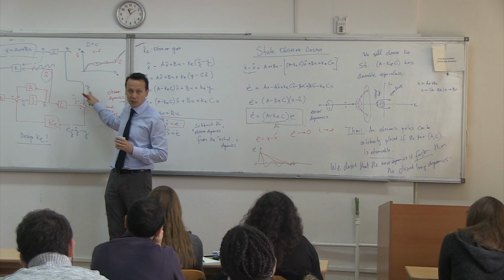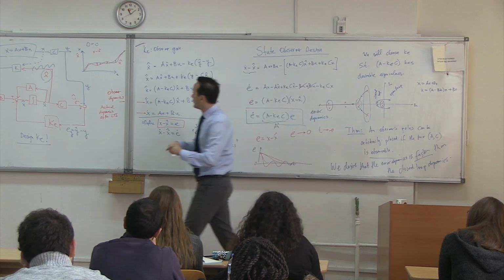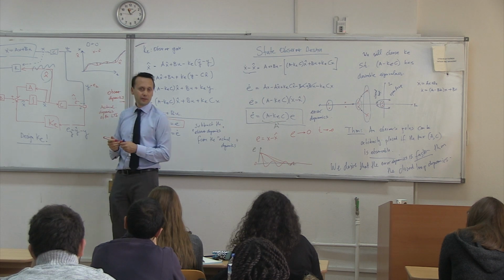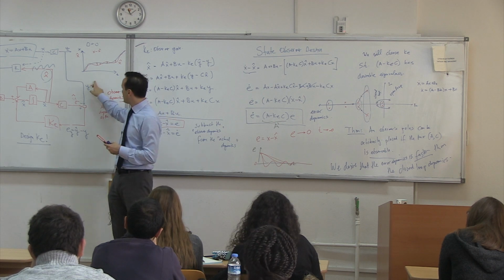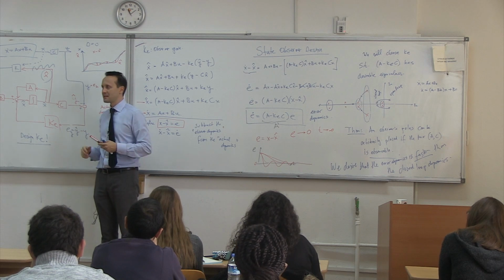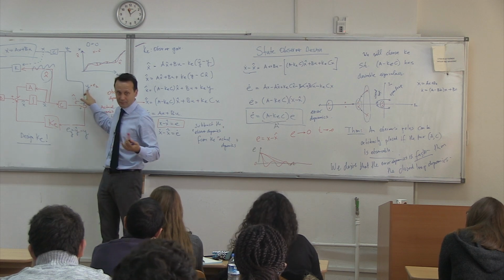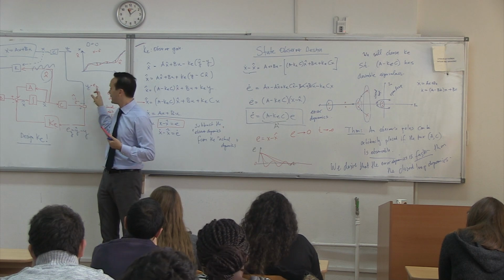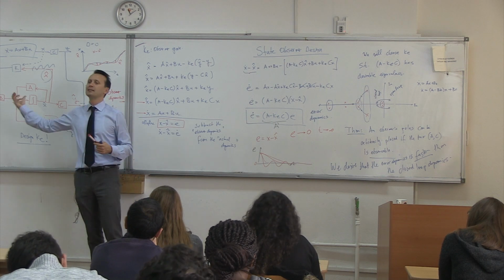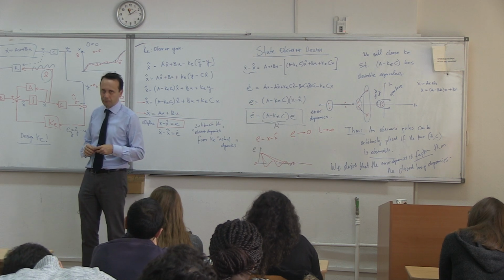So if the measurement is y plus some measurement error, then you're multiplying this error also with this k, which will cause all sorts of problems inside. Because you're multiplying not only the measurement itself, the real value, but you're also multiplying the error with it. So you take this error and multiply it and send it into the system. So a lot of things will happen there as well. So you don't want that.